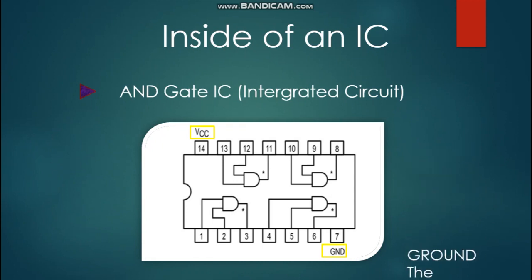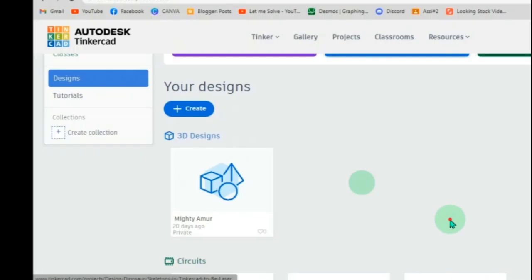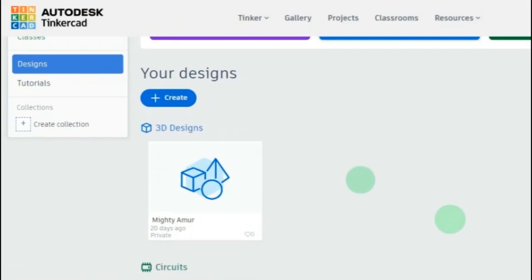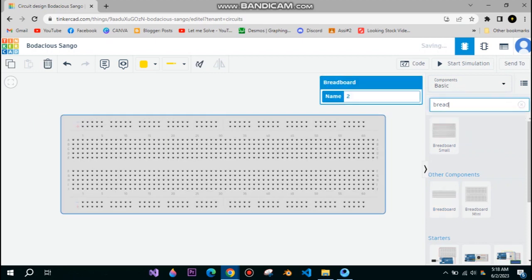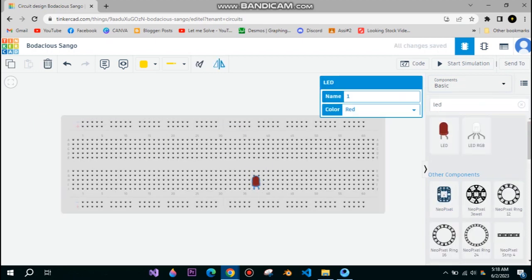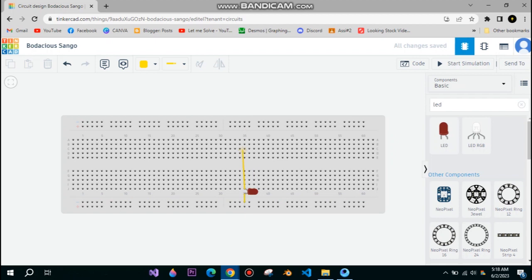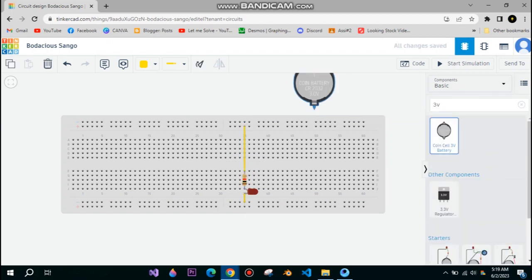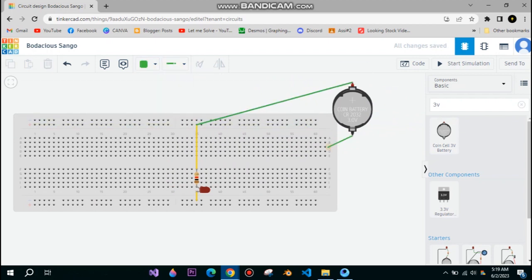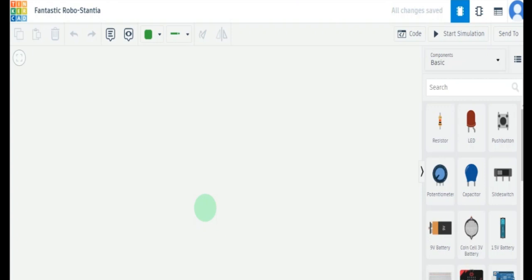Now let's construct a half adder on a breadboard, but on a virtual breadboard. Does it work the same as the real breadboard? Yes, exactly. It is well-designed software called Tinkercad, in which you can design circuits as well as display their results. To make a virtual breadboard, sign in to tinkercad.com and create a new circuit. Now a new empty circuit project has been opened.